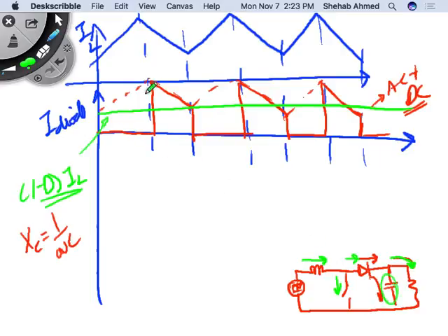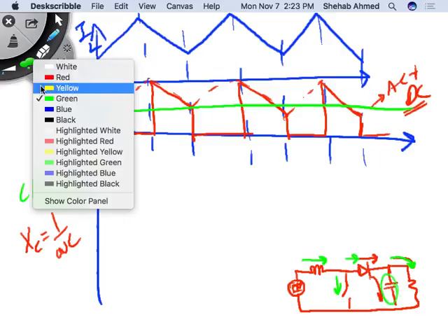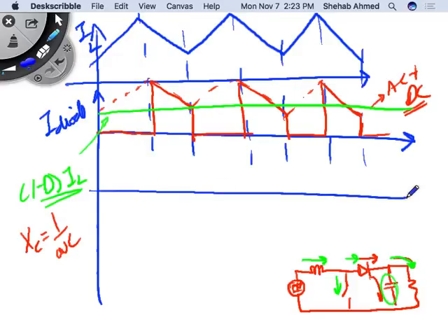So I will take this instantaneous current that's flowing through my diode, remove its average value, because that's going to go straight to the load. And then everything else will flow into the capacitor. We agree? So basically I'll take this and bring it down, like we did before for the inductor voltage in the previous converter. Right?